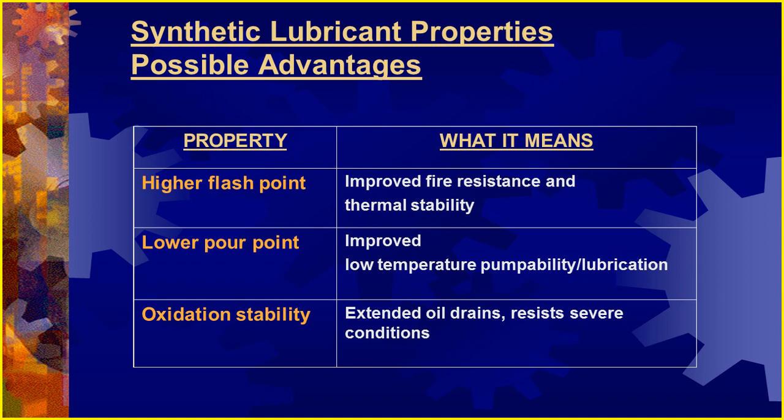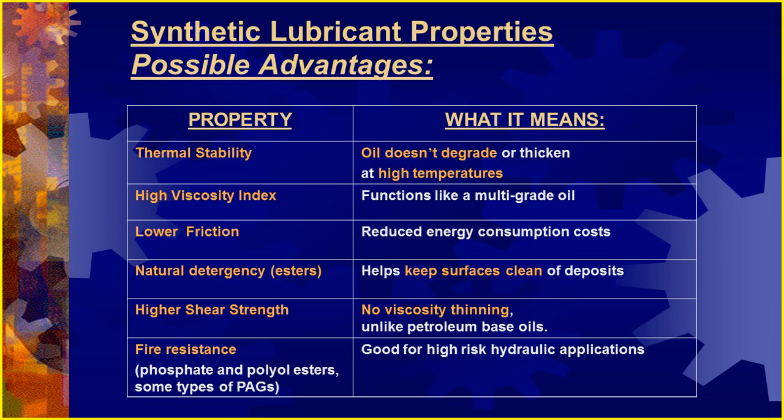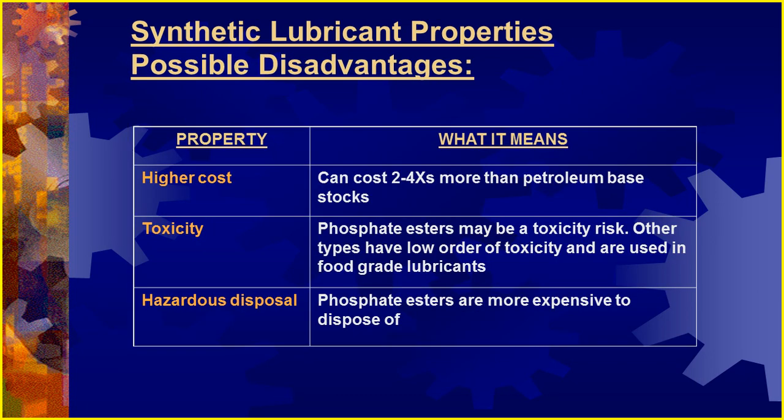Synthetics have greater advantages for higher flash point, lower pour point, and tremendous oxidation stability. The continued advantages are, as we shared, thermal stability and high viscosity index. In other words, it provides viscosity stability through use. It doesn't go up and down as much. Natural detergency, the esters that are in it, high shear strength, and fire resistance.